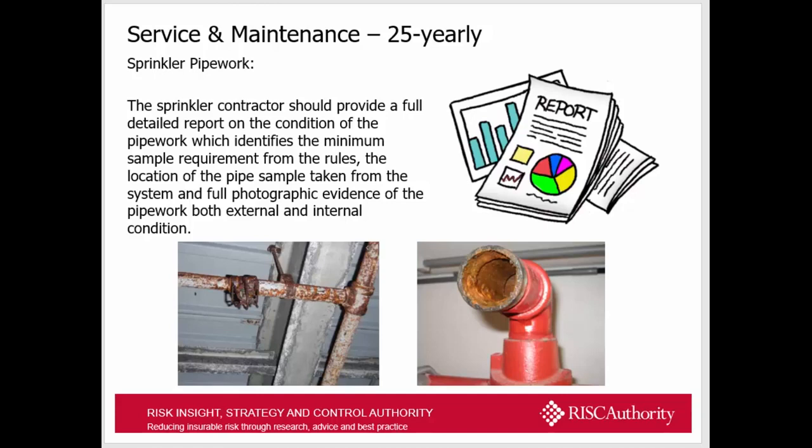So the service contractor removes a pipe, inspects the external condition of the pipe, the internal condition of the pipe, and takes photographic evidence to prove that the pipe has been removed, and it goes in a report. From there, if the pipe work condition is of sufficient issue, then that would need to be sent off for further analysis.